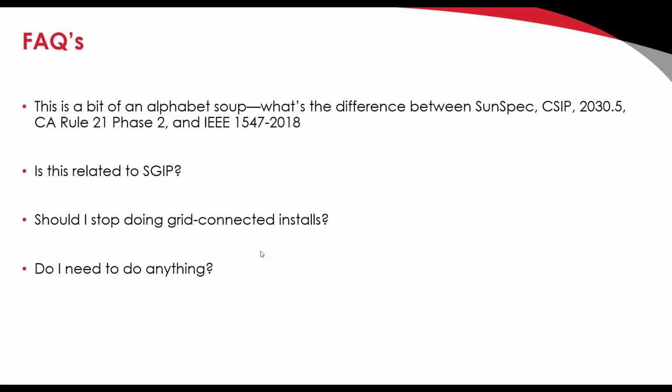And so in order to do that, we came up with this CSIP standard, this common smart inverter platform and the requirements therein. What we decided as part of that effort was that we would mandate, today at least, that we use the IEEE 2030.5 communications protocol for secure communications. And in future, the groups that are working on IEEE 1547.1 2020, test requirements there, there may be some additional standards that are added to that, but today we're all sticking with, as an industry, standardizing around this IEEE 2030.5 communication standard. And that's just a means of transferring bits and bytes from one place to the other in a secure fashion.